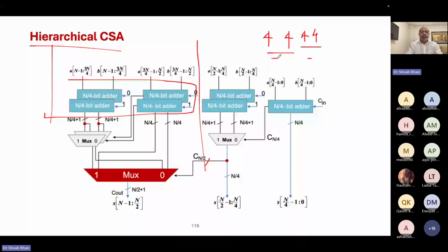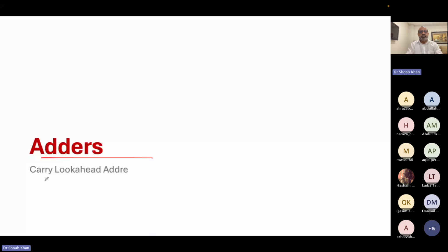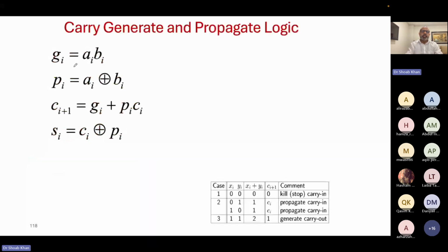So then people have another type of adder, which is carry look ahead adder. I said, why not look ahead for the carry, generate all the carries upfront? And how could you do that? It says generation. The carry is actually either both the bits are 1, so you will always have a carry, or there is a propagation, that if the previous carry comes, then one of the bits is 1, it will be propagated. So either you are generating or you are propagating a carry.